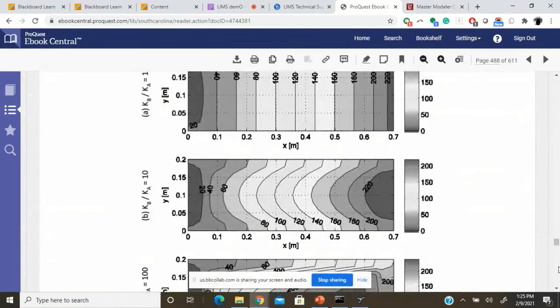so that yeah. So before going into the depths of doing the demo, from our basic understanding of the physics of flow through porous media and the phenomena of race tracking and voids being present, we understand that when it's a perfect mold and it's perfect vacuum condition and perfect injection, we see the mold filling pattern to be very linear.